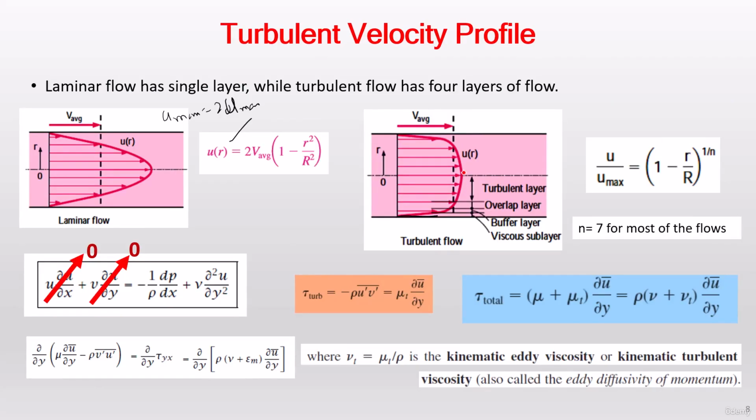And also you can see one kink here, something like a discontinuity. This is a part of the turbulent pipe flow as well, and it is given by the relationship here, where this is the u maximum. So I can write it down for laminar flow, u upon u maximum, which is also a function of r, equal to 1 minus r square upon R square.